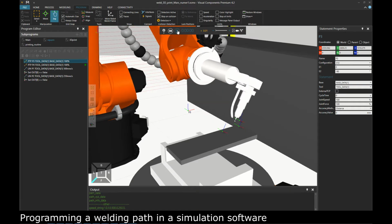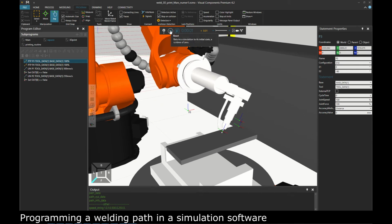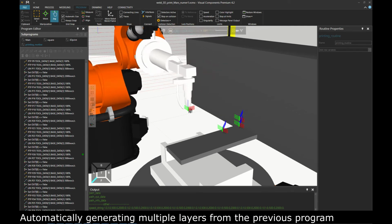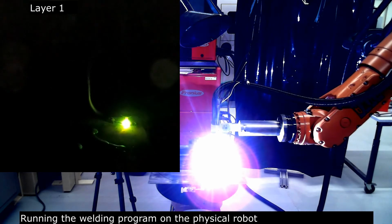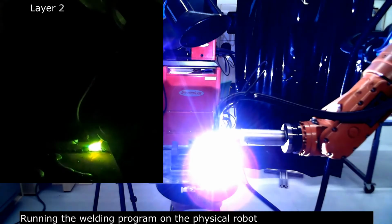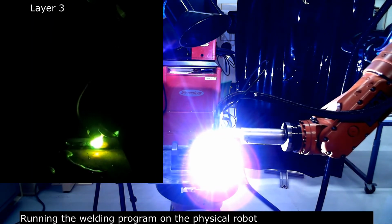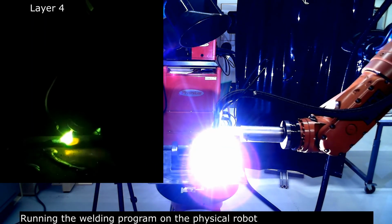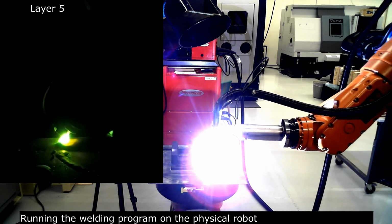I will also showcase a second example of using the 3D printing. In this case, the 3D printing is enabled. First, we program it, but in this case, we are also directly connected to the physical robot. So after we have programmed the system, we then transfer the program over to the physical robot, as you can see here, and then we are running multiple lines of weld and building up a thin wall structure. And this is all completely automatic. And in this example, we are 3D printing 7 layers.